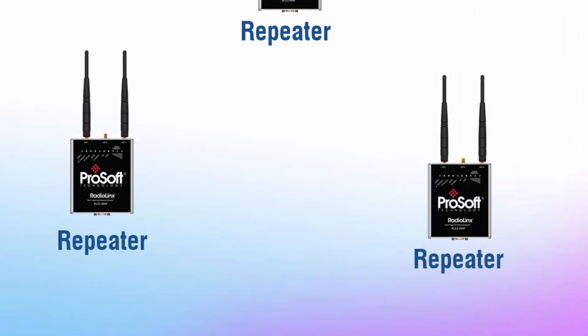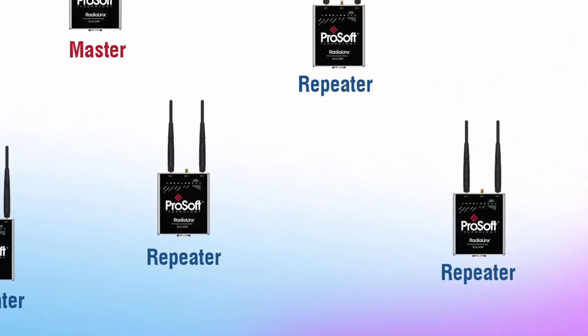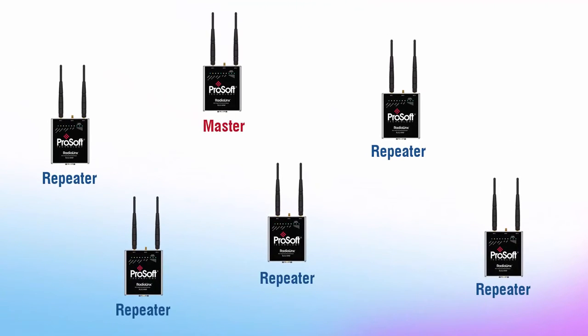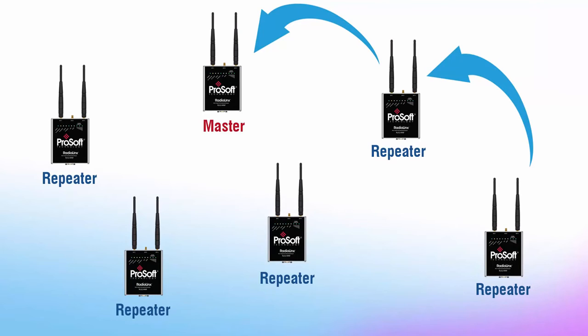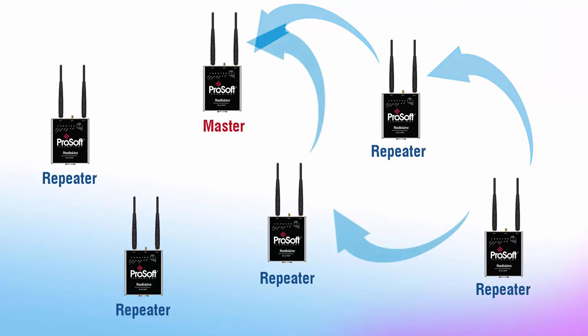Also, if you have a repeater talking to one or more other repeaters to extend the range of your network, be sure that each of the radios in the path are configured and linked together in the proper sequence. If there are multiple paths of similar length back to the master, repeaters may switch between them based on what path they detect is the shortest at any given time.